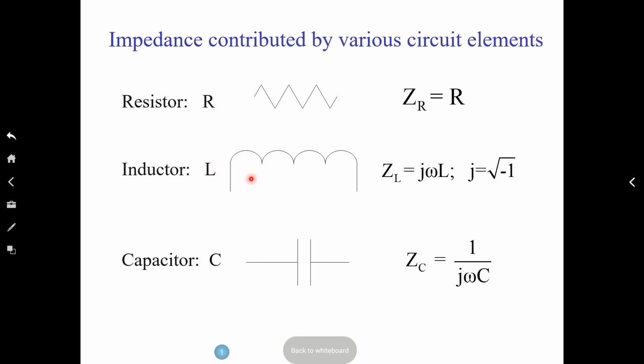How can you get rid of this? Well, one way that you can do it, you can take, for example, a two-bore alumina tube. It has two holes. And you run the wires through those holes, and make sure that they're straight and parallel, and that they're not sagging. That's one way to get rid of your inductive component that is coming from an experimental lead. There are other things you can do. You can write the sample of platinum connection to get rid of some of the other experimental anomalies, but let's not get into those right now.